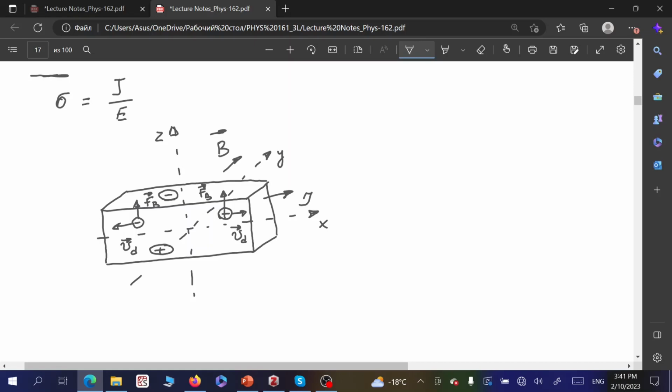So we used to have electric field driving force along axis x for running current through this sample. However, because of interactions of mobile charge carriers with magnetic field, we create this redistribution of charges, and there will be some potential difference between the top and bottom edges of the sample. So we consider between these edges. So this will be VH, so-called Hall voltage.